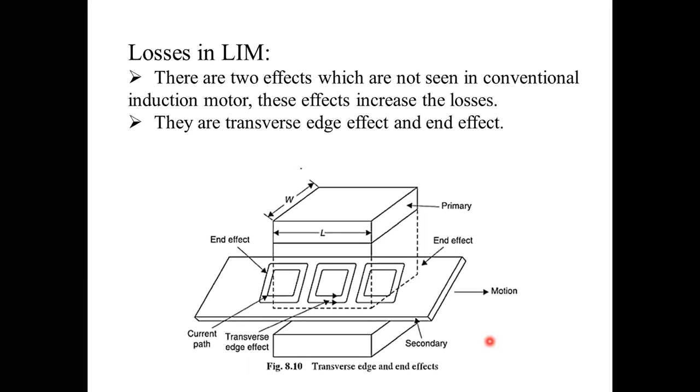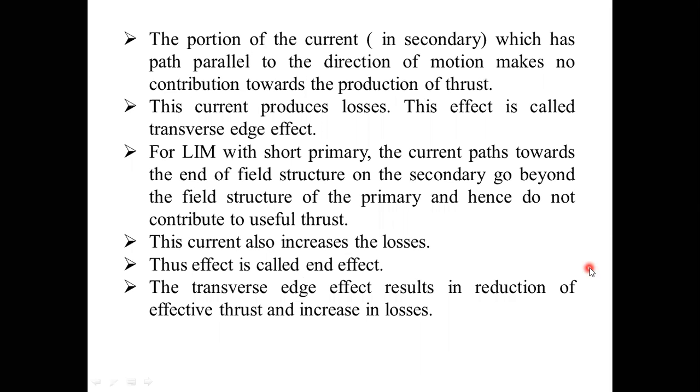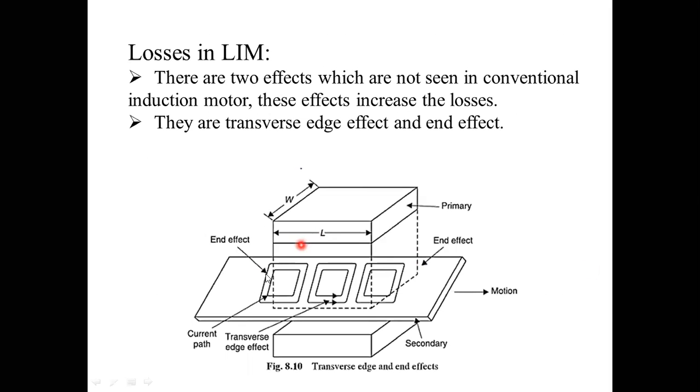And here, some losses are there with respect to the linear induction motor. These losses are not observed in normal induction motors, but we observe them in linear induction motors only. Those losses are called the transverse edge effect and the end effect.